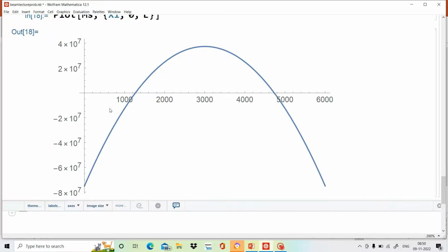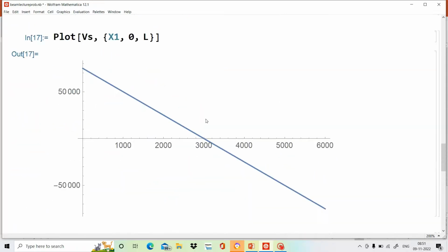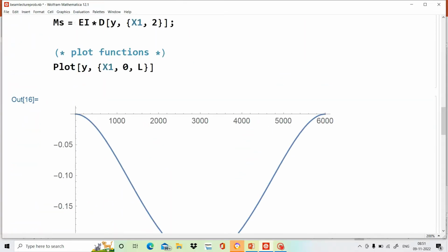So we know that in RCC design we put the steel also at the top for the negative moment or tension to carry the load. So from this diagram we can get how we design the steel in the RCC beam. These are required for design purposes. So we have seen the clamped case, the bending moment diagram, shear force diagram, as well as the deflected shape.